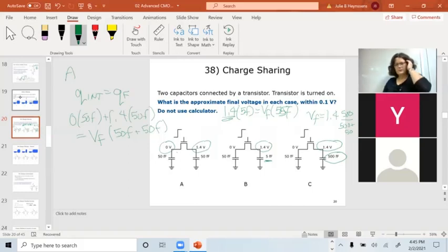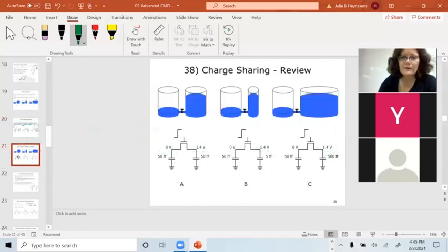What happens particularly in memories, you try to charge a 2 femtofarad bus with a 0.2 femtofarad capacitor. And it goes up, but it only goes up like 50 millivolts. So you have to put an analog circuit in there to read that and take it and put it into a real voltage. I just talked about that last class. So yeah, the buckets of water are just like these buckets of charge. A big capacitance is like a big bucket. A small capacitance is like a small bucket. Okay, good.